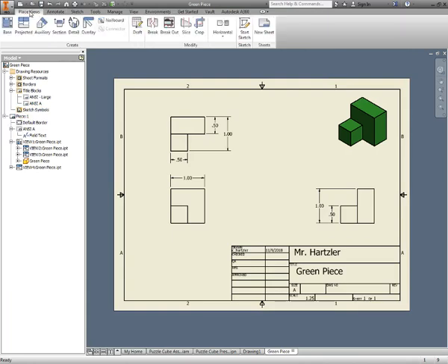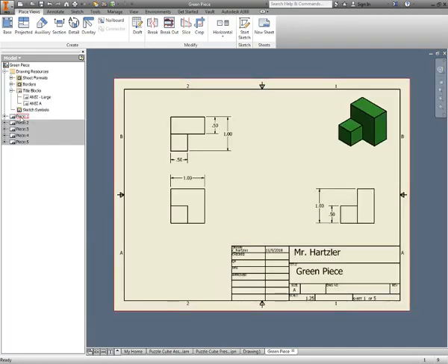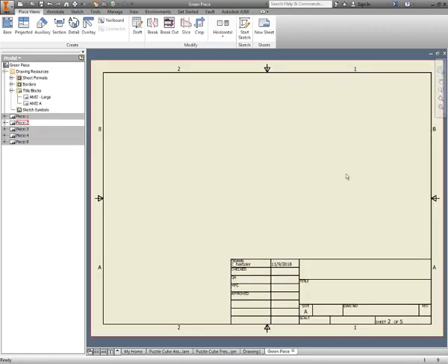If you're in Place Views, this is up here in the top left corner. If I'm in the Place Views tab, I can hit New Sheet, and it will keep adding new sheets. The puzzle cube takes 5 of them. So now I have 5. I just kept pressing New Sheet until I had them all. The first one we did should be piece 1. Double click there, and it should take you to here. You want your next sheet? Double click on it, and it'll take you there. Everything should be edited and fixed, and your little title box should be good to go.